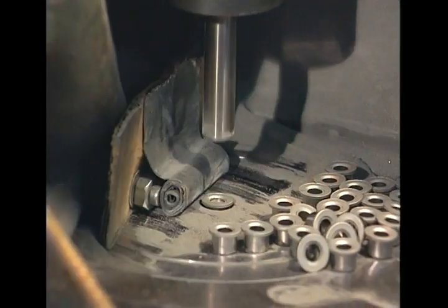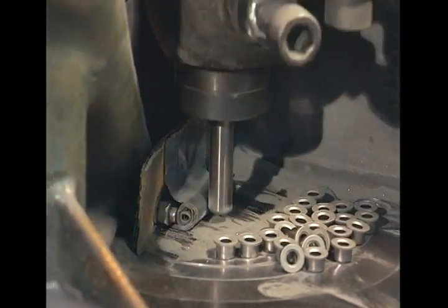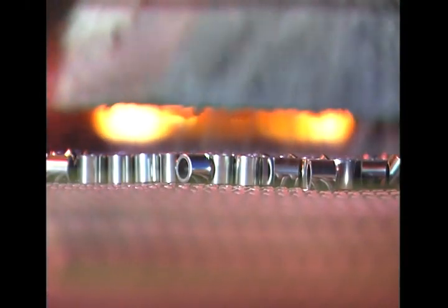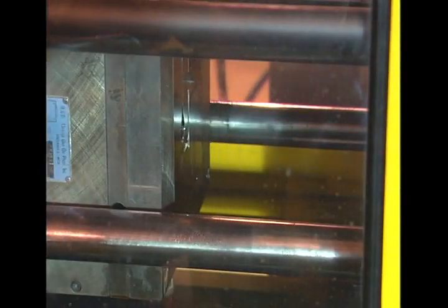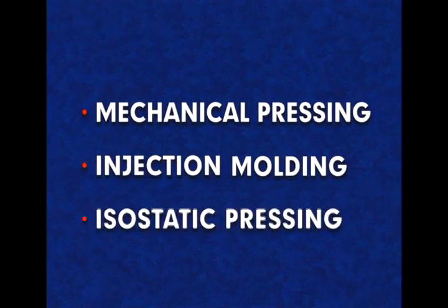The powder is then consolidated in dies or molds, shaping and densifying the powder into a compact of the desired part. The compact, which is in a green state, is then sintered. The common methods of consolidation are mechanical pressing, injection molding, and isostatic pressing.